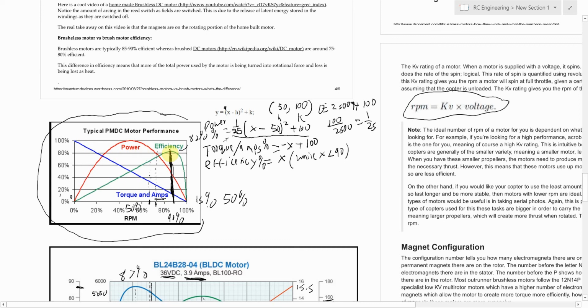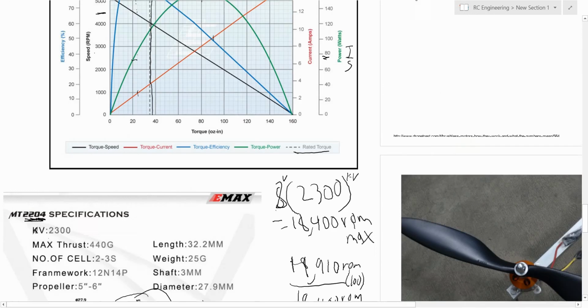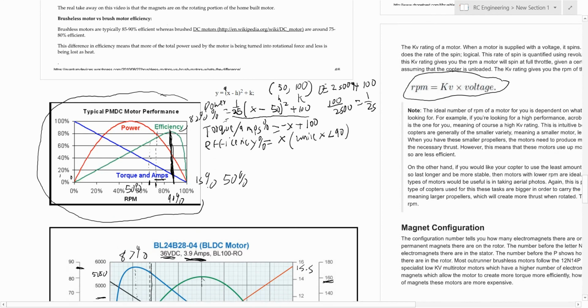And we'll learn in the gearbox video that a reduction gearbox basically means the motor has a smaller gear on it than the gear that turns whatever you want to turn. So as you see down here, the gear that turns the prop, which is that guy, is quite a bit bigger than the gear that is attached to the motor. So that is a reduction gear. If it's the other way around and you have a bigger gear on the motor and a smaller gear on whatever you're turning, that is an up gear, I guess you could say.